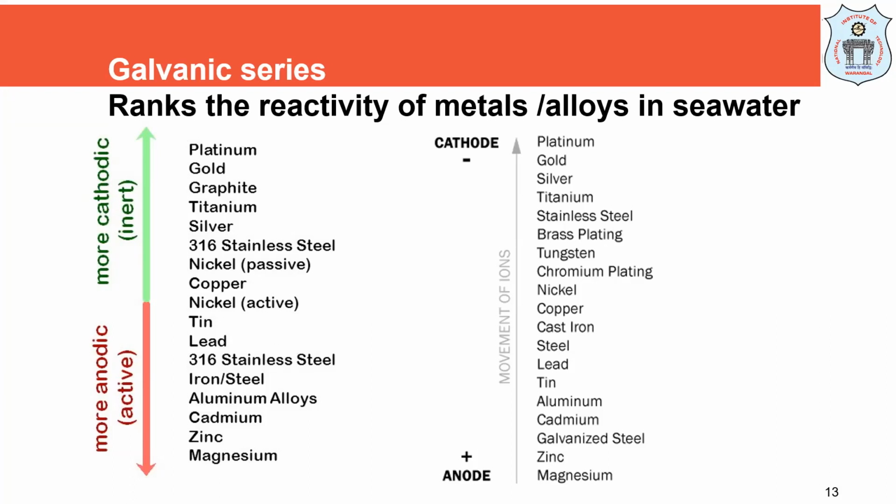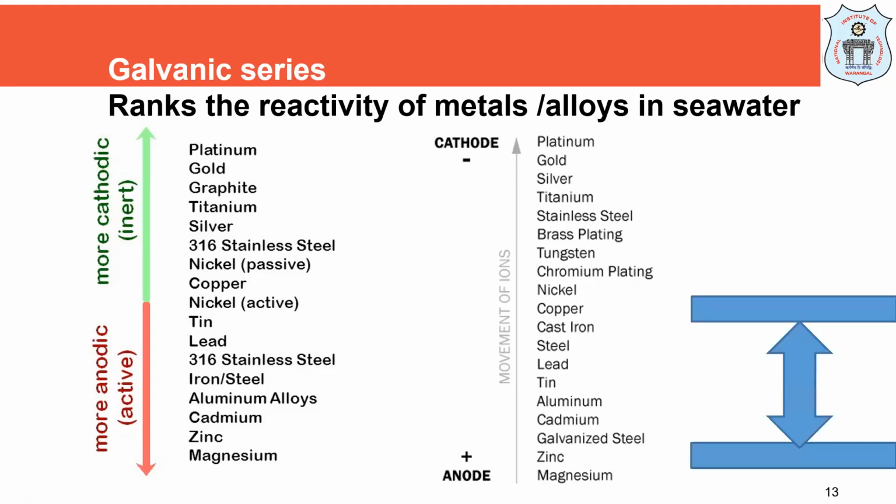Okay. So when you connect them in series, remember this galvanic series reactivity changes with the environment, right? So this is arranged particularly with the seawater. So when you are having different environment, you are going to choose accordingly the materials to be connected.